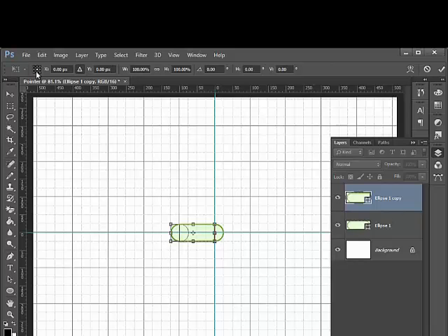The reason for removing the circle from the arrowhead blade is because you can choose any grab handle as a point to rotate about. We want to rotate the blade out from the stem, but if the circle was still there, there wouldn't be a grab handle at the center of the tip of the arrowhead. Up on the Shape toolbar, select the grab handle at the middle of the right-hand side of the blade. Now, by hand, rotate out the blade until it looks about right. That looks good, at least to my eye, and the angle is about 35 degrees.